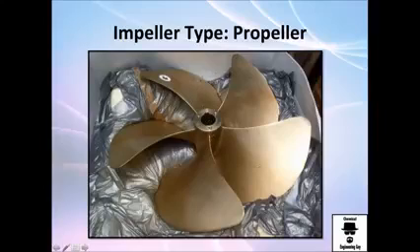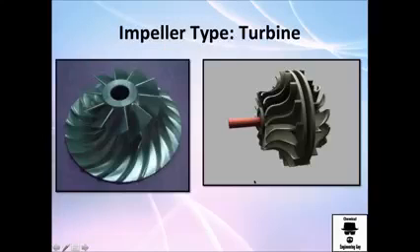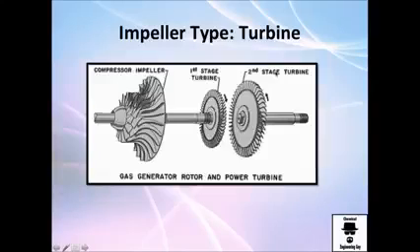Another example of the impeller or the propeller. All propellers are impellers, not all impellers are propellers. So a propeller, as the name implies, propels the fluid. Now, impeller type turbines, well, as you can see, it's very similar to those turbines you've been studying in thermodynamics and even in pumps. And you don't need to be a genius to know that if it moves, it is going to move the fluid. Some example of how you can build one: you have the upper disc and the lower disc.